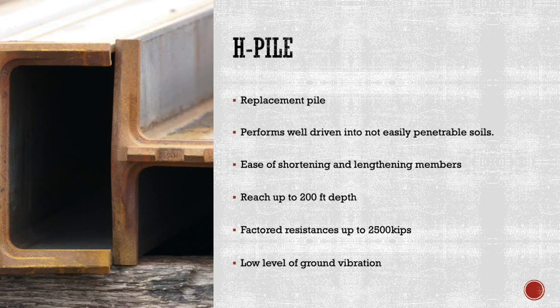It is a replacement pile, having low impacts on soil and leaving the surrounding soil undisturbed. It does this with little to no vibration, causing no effect for surrounding structures. It performs well being driven into dense, hard soils, also having the ability to break through boulders and reaching depths of up to 200 feet.